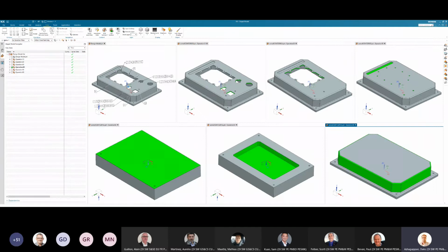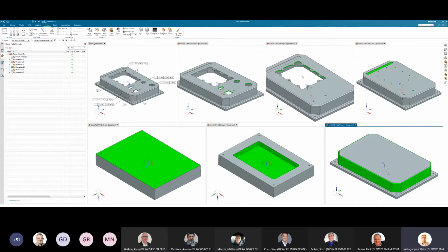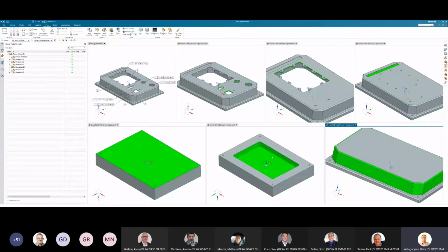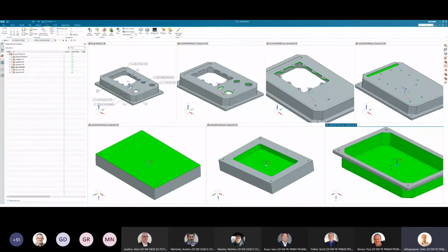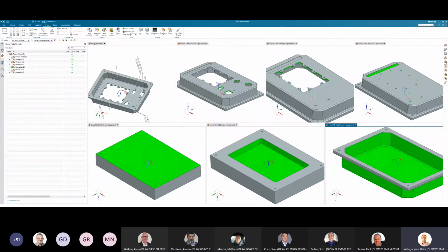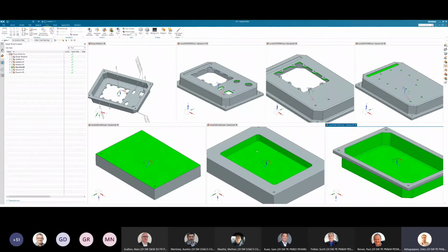So basically you can see here, start with the design model. I have basically 6 different operations. So going through operation 10 through operation 60, you can see all of them over here, right? In operation 40, I'm mentioning the top pocket here, and also finishing up the center pocket. And then in operation 50, I need to machine this to a smaller shape in order to get to the final shape in operation 10. And then I have operation 60, basically from the cast model, where I'm mentioning the top datums.